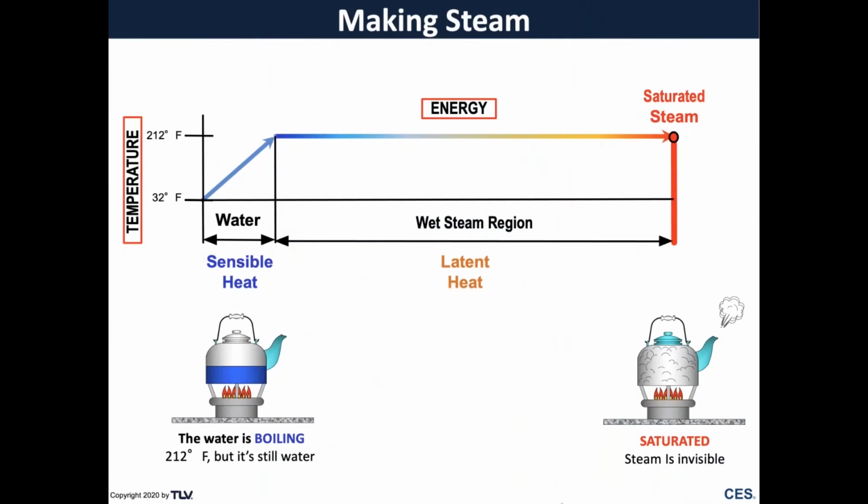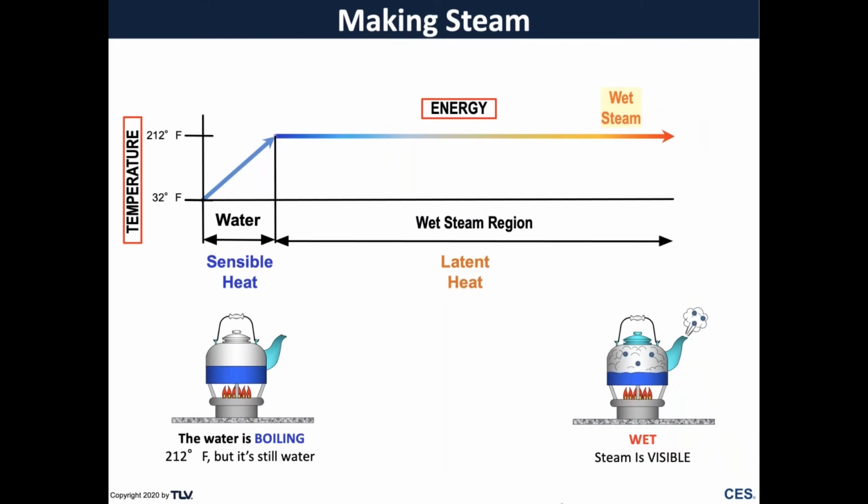So let's take a look at making steam again. You don't have saturated steam. You got wet steam. It comes off at the boiler about 95 to 97% dry, which is 3 to 5% wetness. You have uninsulated flanges. You have missing insulation. You have insulation that's only 80% effective. So it gets wetter as we go on. So is it 90%, 88%? Who knows? Slurries in Alberta can have 30% wetness in them.